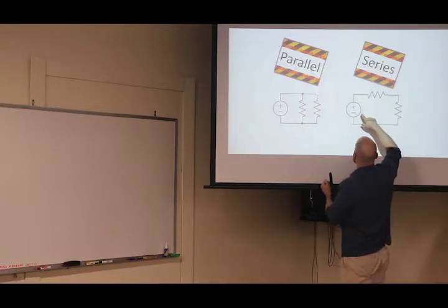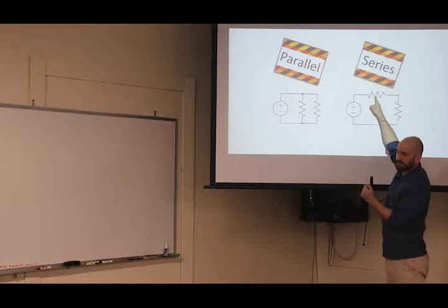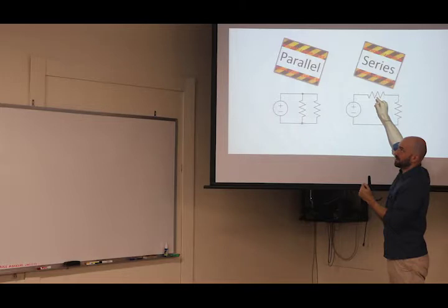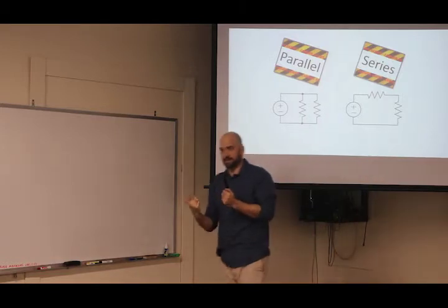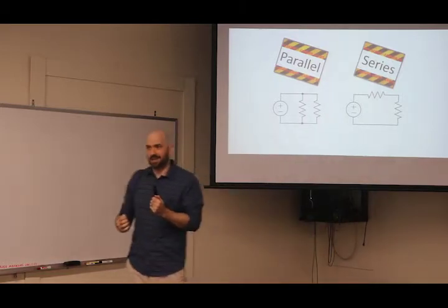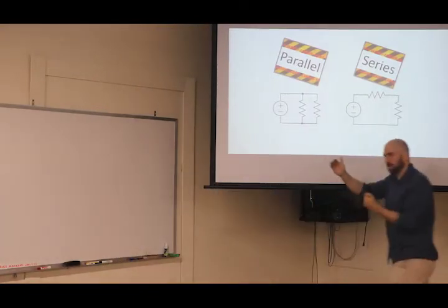And then you have that many amps crossing this resistor. So you can figure the voltage drop because you have the resistance and you have the current. So they each have 4.5. Yeah, if they're the same resistance. You can take it to an extreme case.